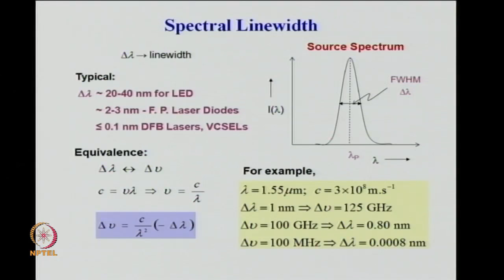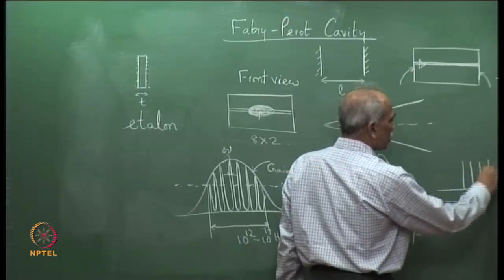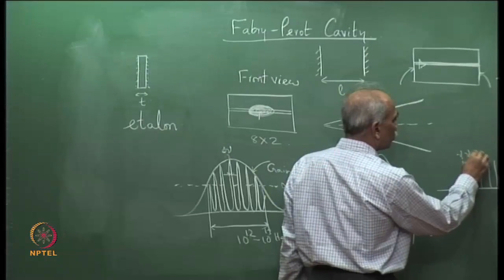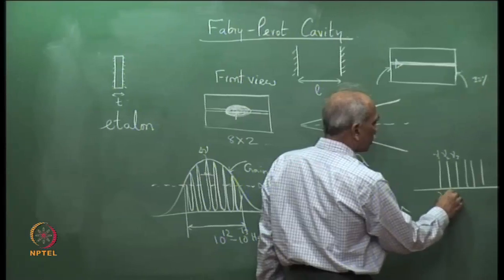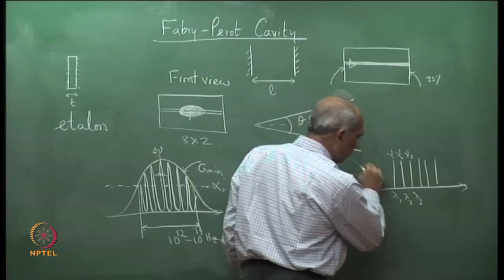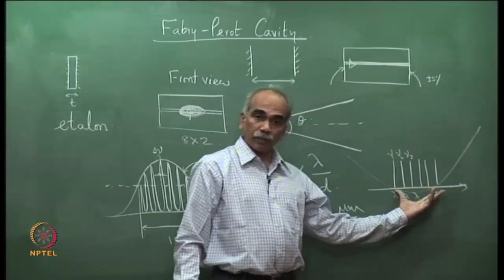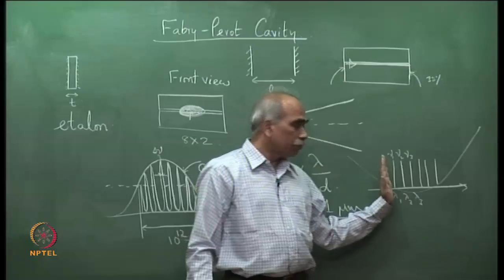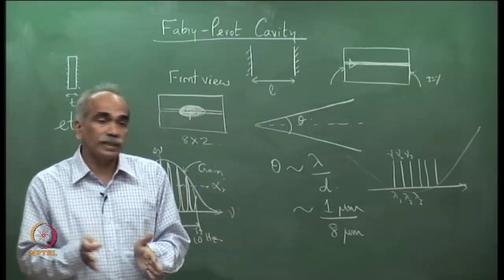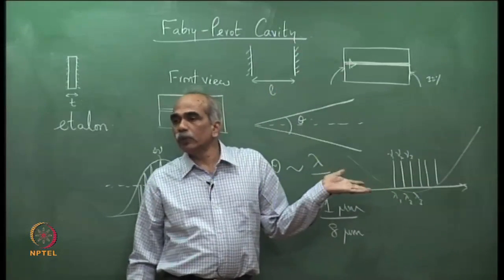Many of you may not be aware that in a DWDM system you put a large number of wavelengths, frequencies nu 1, nu 2, nu 3, or lambda 1, lambda 2, lambda 3, in the 1550 nanometer low loss window of optical fiber. Around 1550 you can pack a large number of closely separated wavelengths into a single mode fiber, which makes the DWDM system.